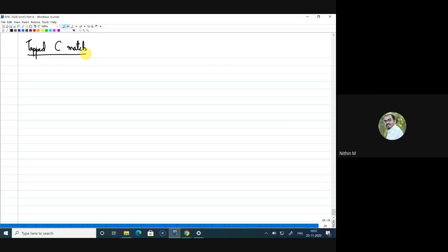in the case of L match, the Q factor is automatically determined by the impedance transformation ratio. But in the case of pi and T match, the extra degrees of freedom let the designer work on the Q factor. In a similar way, this tapped capacitor resonator also has the ability to set values like center frequency, Q factor, and the impedance transformation ratio.